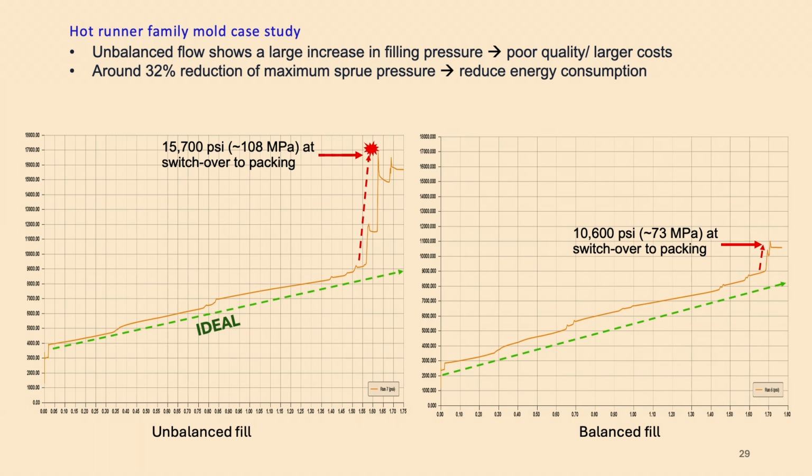So this not only solves the poor quality issue that may potentially occur, but it definitely helps reduce energy consumption. From the pressure decrease of around 72%, we can imagine that from the original, maybe at the beginning of the injection process, there are even more energy savings from the reduction of injection pressure.